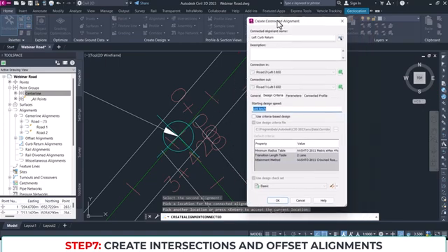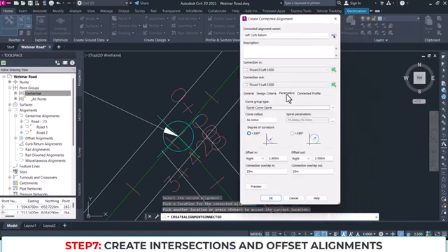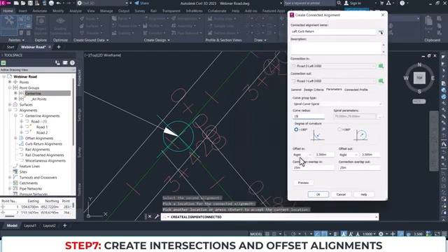Where do we find that? You can find that under parameters. So the curve radius is going to be, let's say, 15 in this case. And the offsets, I don't want any offsets. If you're using 2018, you won't find this, but if you're using 2023, you'll find all these things here. So I don't want any offset to the left or to the right.